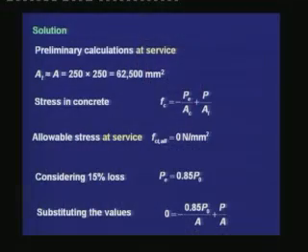Next, we are doing the preliminary calculations at service. There we are assuming At is equal to A equal to 62,500 millimeter square. The stress in concrete can be calculated by this expression which we learned in the module on analysis of members. Fc is equal to minus Pe divided by Ac plus P divided by At.